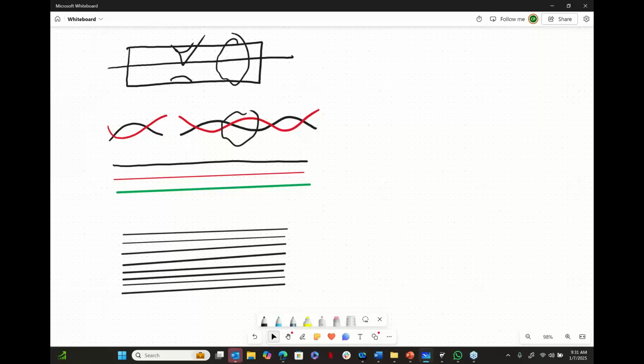If water can be pinpointed in a cable, there are many things that'll let you know you have water in a cable, but a TDR still is the best thing, bar none, for being able to pinpoint where water is. But also, typically when you have water in the cable, you're going to have 2 issues, right? Where it came in and where it migrated to. Still, TDR is your best friend.